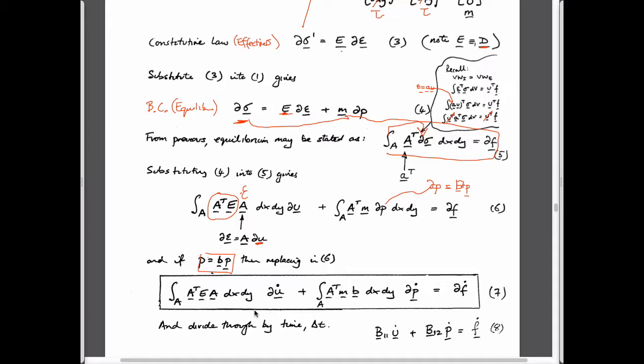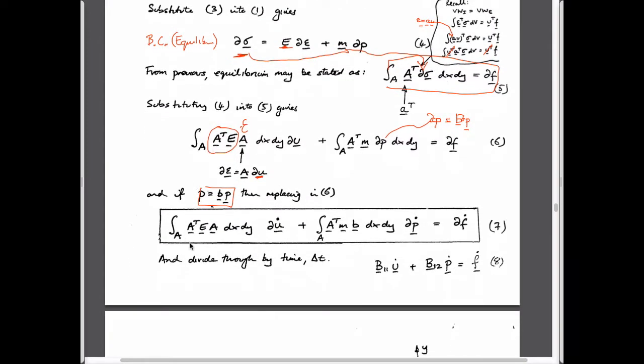It's equal to something that we've seen before. This A transpose dA is what we've had before, right? I've written it in uppercase A to make the distinction, because these are the ones for the strain displacement equation. So epsilon equals AU. There's a reason for writing it as an uppercase A: it relates the strains and displacements to each other.